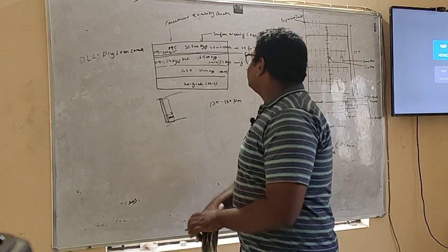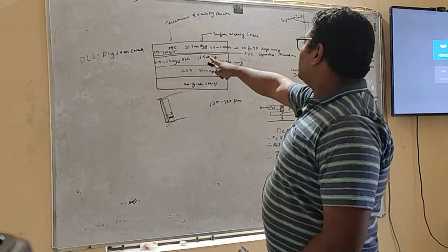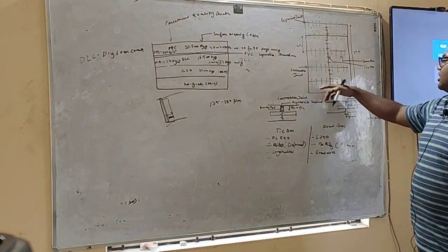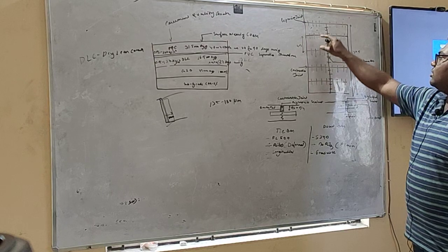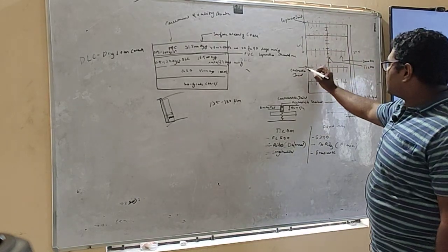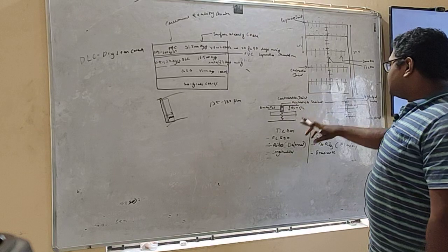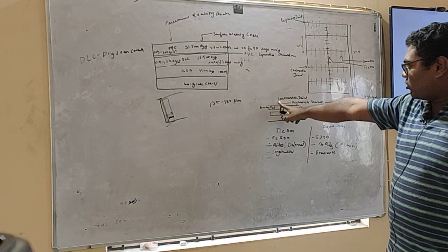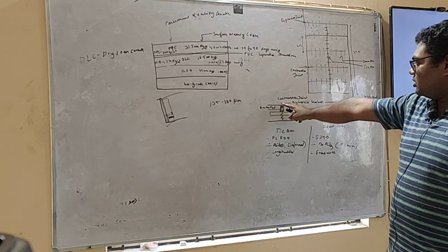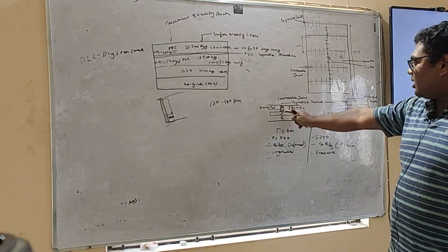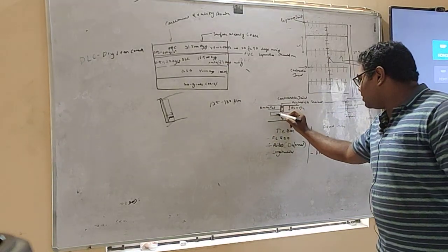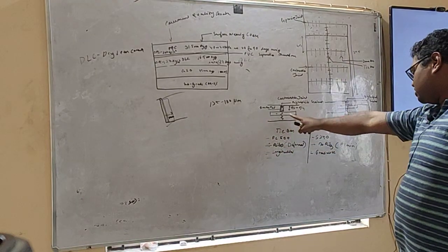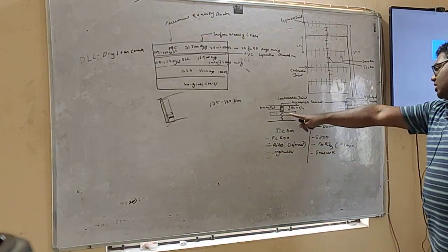And after laying our PQC, we will give a surface wearing course. Again, coming into the PQC, we can see that it is separated at a 4 meter interval. These lines are known as contraction joints, and these are basically here to prevent cracks. So in contraction joints we artificially make a crack, and inside it we put a tie bar which should be of FE 500, which is dowel bar. Sorry, my mistake. This is dowel bar.